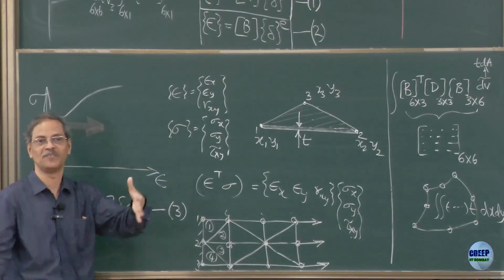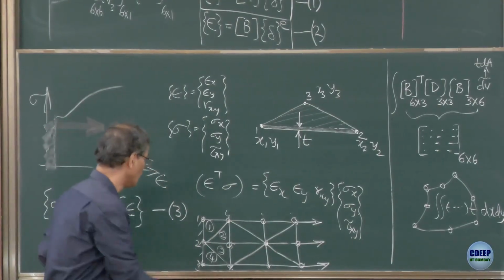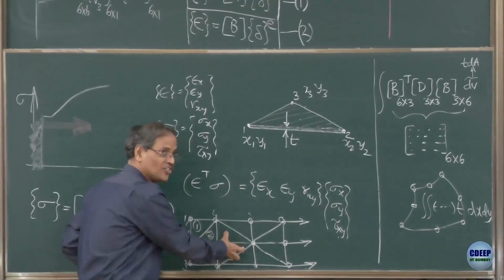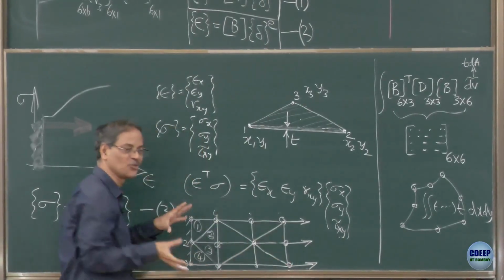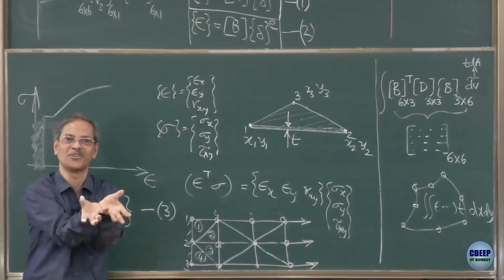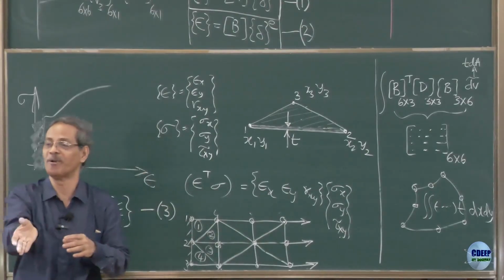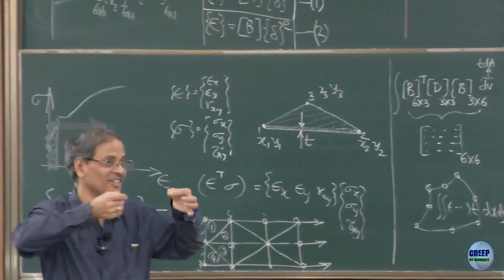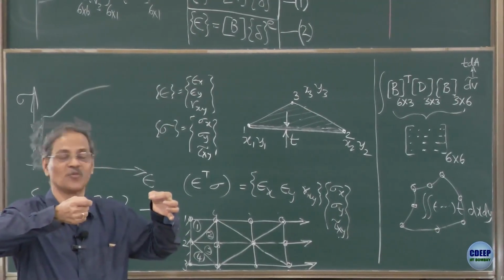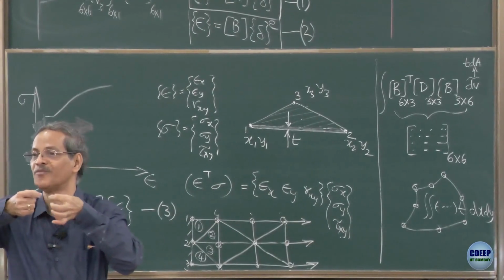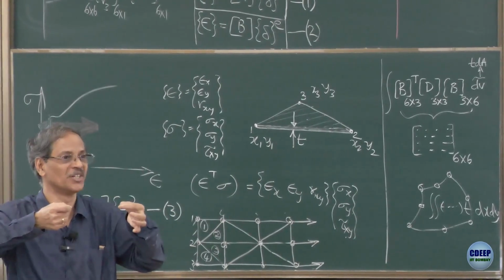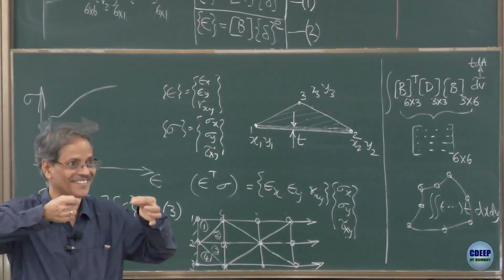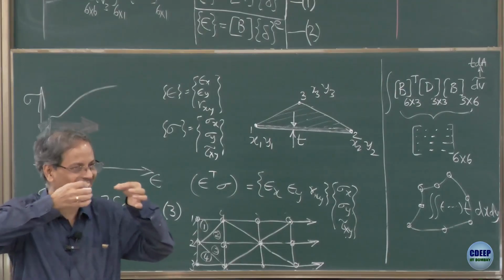Okay. Now imagine if it's a plate with a circular hole in between. So I will need to take a lot more elements to capture that circular hole geometry accurately, because stress concentration will depend upon that circular hole. Or if there is a crack, imagine those of you who are involved in fracture mechanics oriented research. So if there is a crack, then it's a minute crack, right?